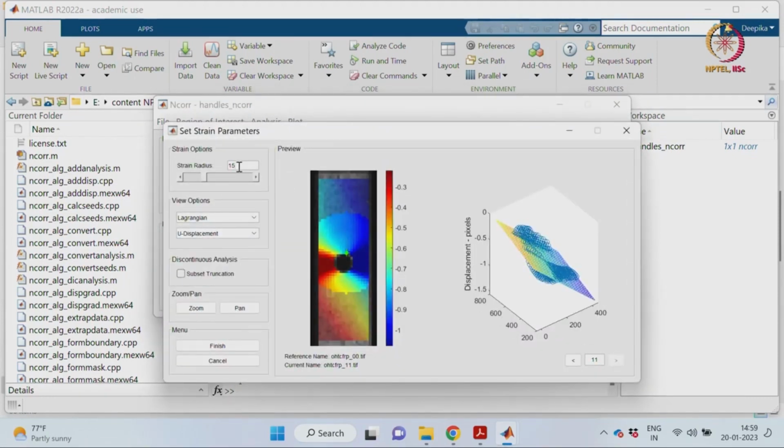Okay, so, if you remember, we have already mentioned that when we search for correlation using the subsets on the grid, we get the issues of discontinuities across subset boundaries in this local DIC scheme. So, this taking the subset from one small grid center and then searching, this is what we call a local DIC scheme. So, at the end we need to have some type of interpolation or some type of curve fitting, which will help us avoid that discontinuities issue.